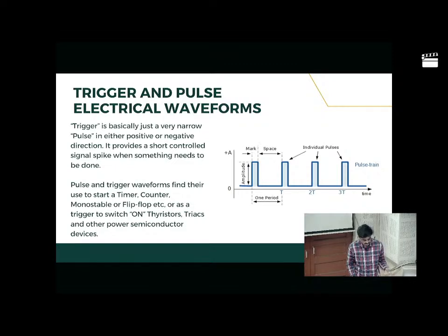And even in power electronic devices, semiconductor switches such as thyristors, which you might be familiar with or might study later in the next workshop, a pulse signal is required to start the conduction, and the thyristor stays conducting until the current through it is reversed. So we just give them a pulse signal and then it conducts accordingly.